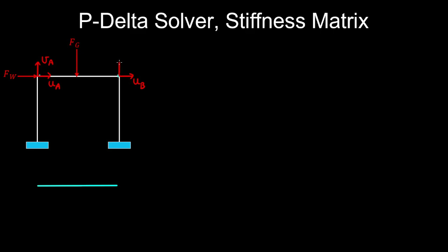and a lateral displacement. And we also have rotations at node A and B. So each element has 6 degrees of freedom. And axial displacements lead to axial forces developing in the element. So I have the axial force at node A for our element AB and an axial force at the other node. So at node B for element AB.